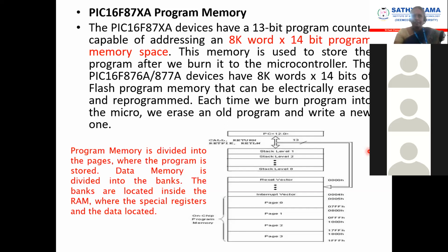We have seen the Keil compiler now. So we will write the program in the Keil compiler. After writing the program in the Keil compiler, if I want to erase, I can erase my old program, and I can write my new program. That's why I told you all these are EEPROM type. It's not a ROM type.